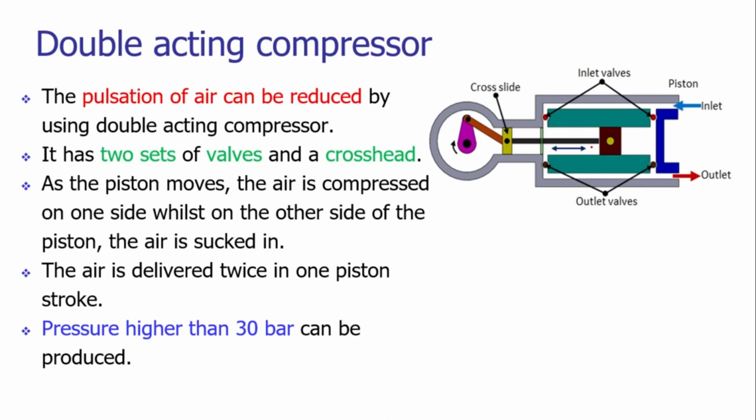So to increase the efficiency of the single acting cylinder, we can also utilize a double acting cylinder. So in a single reciprocatory motion, we can generate 2 times the compressed air. So how? For that purpose, a typical arrangement can be seen on your screen.